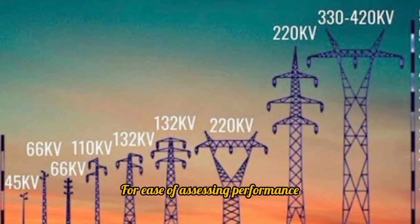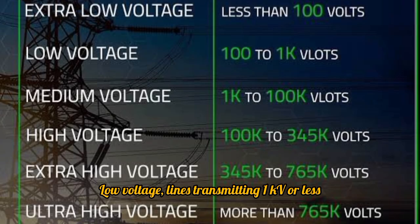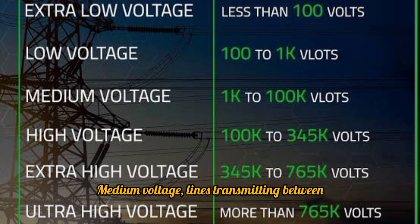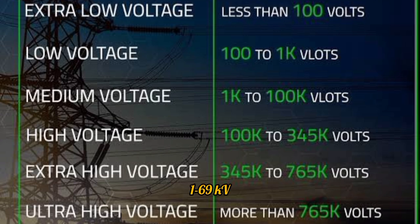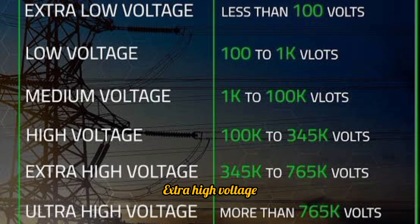For ease of assessing performance, AC power lines can be classified according to voltage and length. Voltage classification. Low voltage, lines transmitting 1 kV or less. Medium voltage, lines transmitting between 1 and 69 kV. High voltage, lines transmitting between 69 and 345 kV. Extra high voltage, lines transmitting around 345 to 800 kV. And ultra high voltage, lines transmitting 800 kV and over.